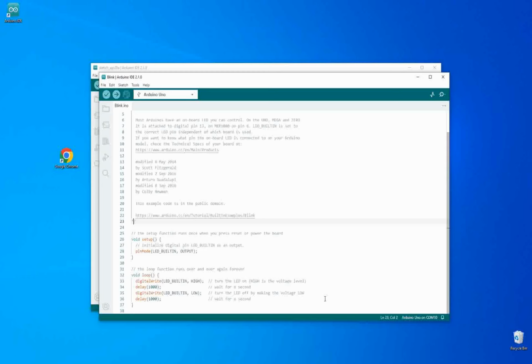In this case, pin 13 will send a digital output signal, that is 0 or 1, true or false, on or off, up or down, or high and low. This signal will be sent every 1000 milliseconds, that is 1 second. What if I want the change over time to be different? Well, we can modify its time by changing the number of milliseconds that have to pass after each command. Remember, most of the code is executed from top to bottom.